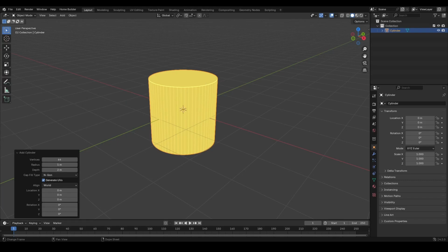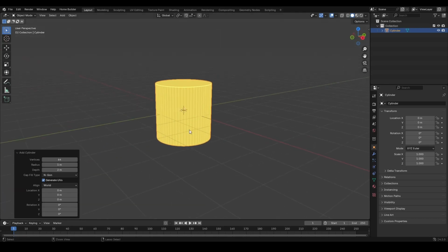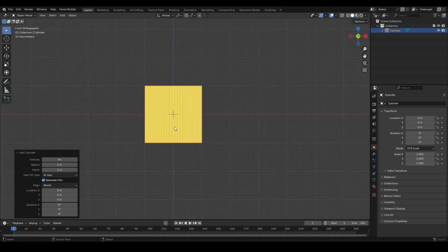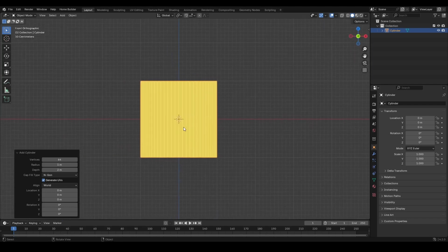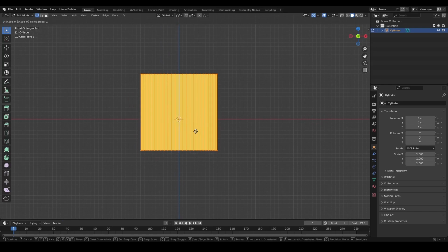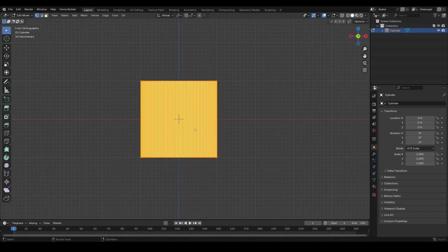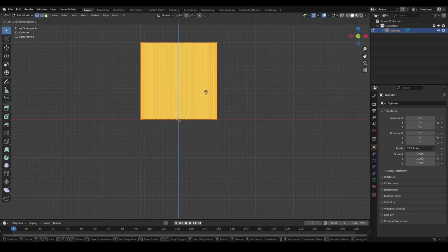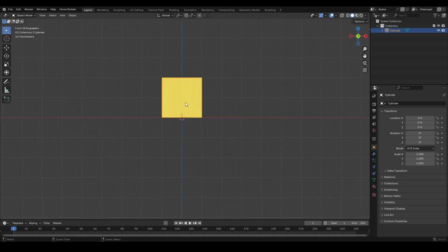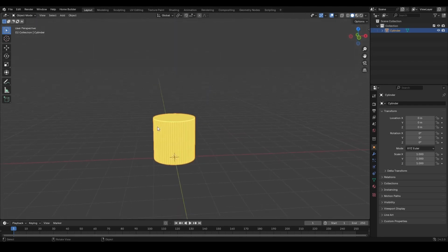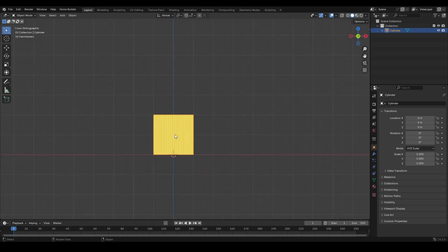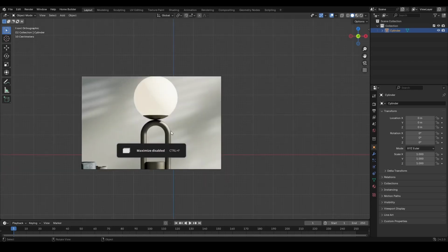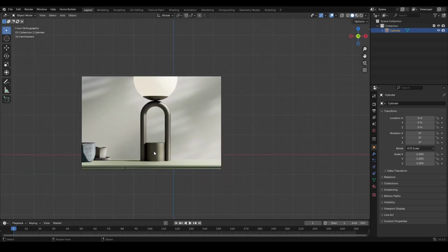I have my image render on the other monitor, and based on that I like to model this out. So we move everything in edit mode. We press A to grab everything, move it up, it's okay. And then for the next shape, this is finished.